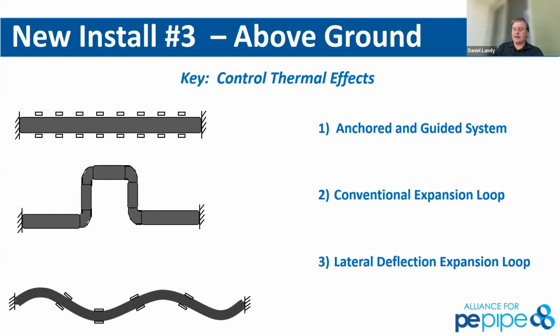Above ground, probably the most difficult method for me to describe. We get the most questions, and I believe that is because we are now getting into installation methods where people don't have their mind primed. No one's used to designing ductile iron or PVC above ground, so we really start looking at all the possible failure situations. Really, no concerns for HDPE, indefinite outdoor service life with that infinite UV radiation.